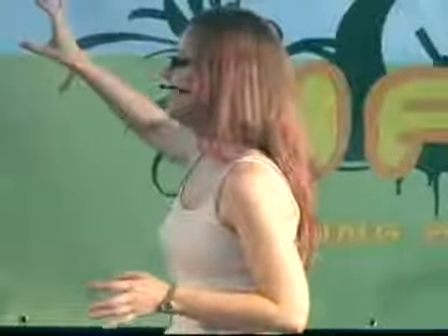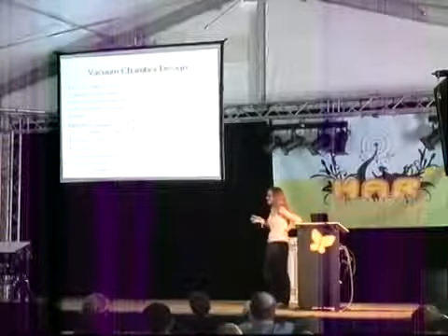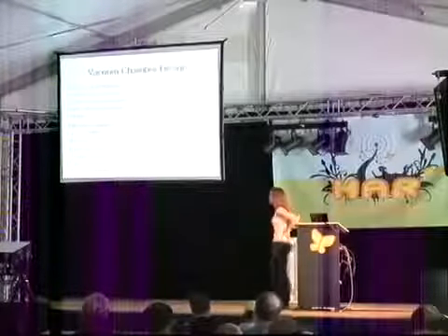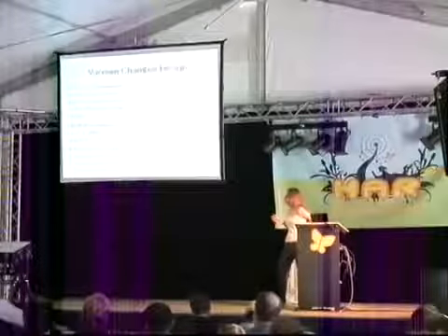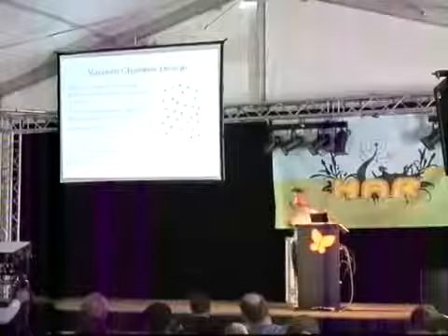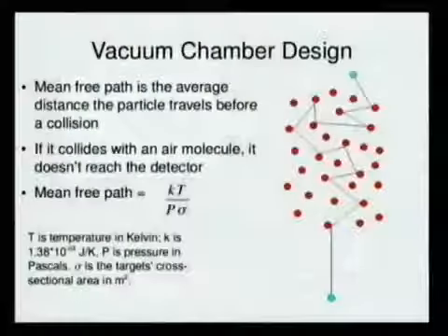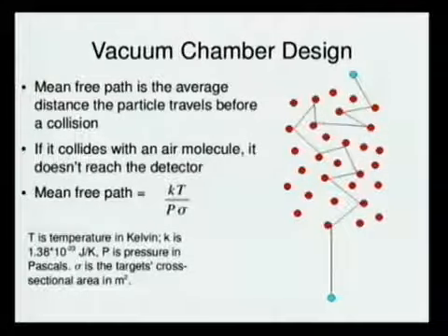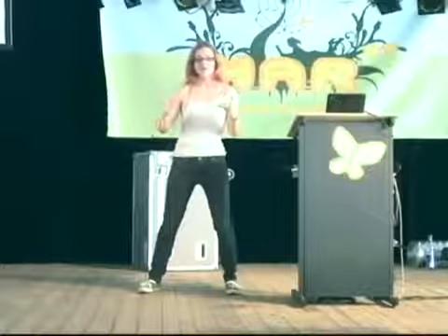So you'll have something on the order of that. So now you know what flight distance is, and easy MATLAB or OpenOffice spreadsheet simulations will tell you what those are. You have to take into account the mean free path. Now, the mean free path is the length of the spiral under real conditions, and that depends almost exclusively on the vacuum pressure. As you can see on this slide, if you have a very low vacuum, almost a perfect vacuum, you only have a few air molecules inside your chamber. If you have a less than ideal vacuum, you, of course, have more air molecules.